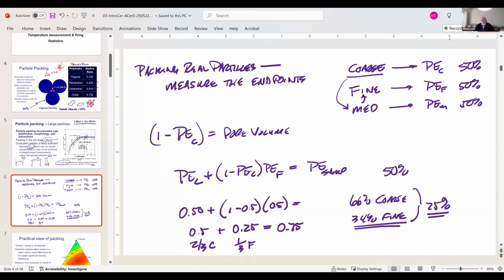If I broaden the particle size distribution, the powders will pack better. In my sand example, sand is a scalped distribution, meaning that the supplier of the sand cuts off the tails, the coarse end and the fine end. And for fracking, they look for a narrow particle size distribution anyway. So they're all narrowly distributed powders, and I don't get a packing benefit by having a broad distribution.